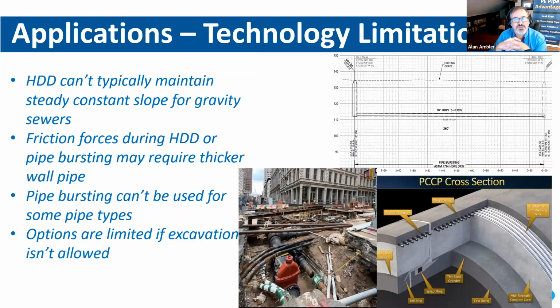And I hate to target PCCP directly, but there's a generation of pipes in the 70s that stretched the material a bit. Statistically, the Water Research Foundation has looked at this, and that pipe in larger diameters has a higher likelihood of failure. And then when we get into big pipe, we have a higher casualty of that failure as it goes through. It's much more painful for a 48-inch pipe to burst and cause some above ground disturbance than it would be for a 6-inch pipe to burst through that.